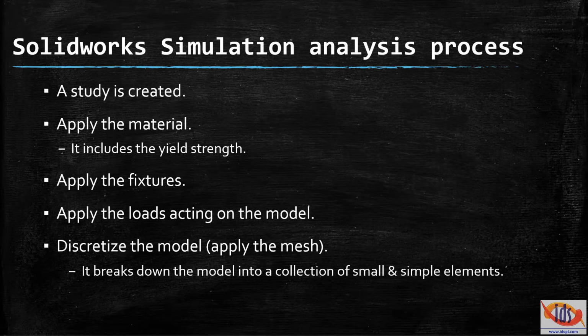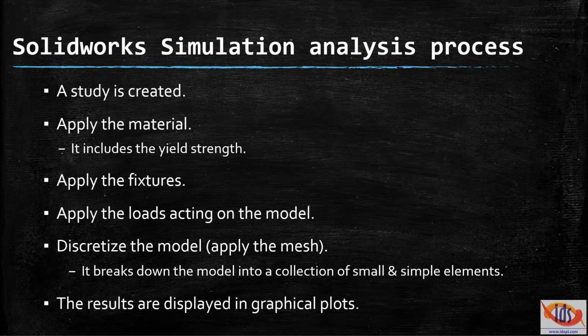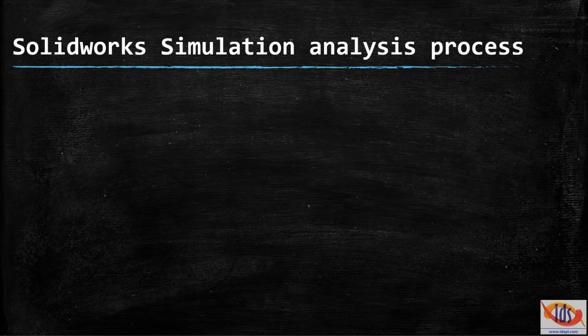This allows the solver to find values such as the stress and displacement at each point where the elements join together. Once all of the previous steps are complete, the study can be run to calculate the results. Finally, the results are displayed in graphical plots according to the result type such as stress or displacement.